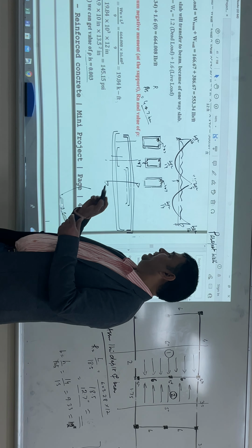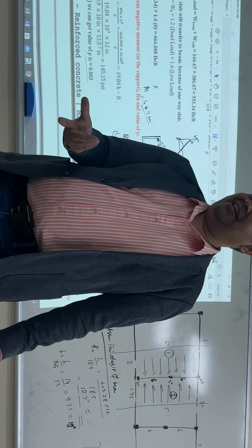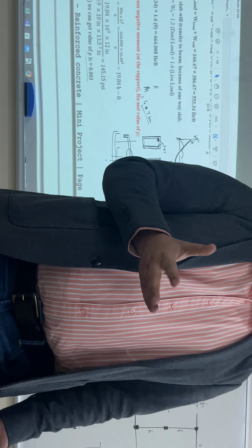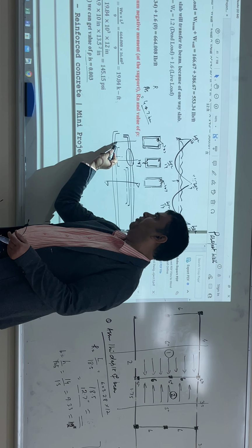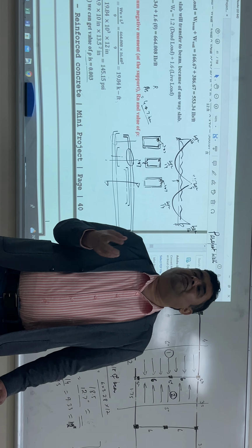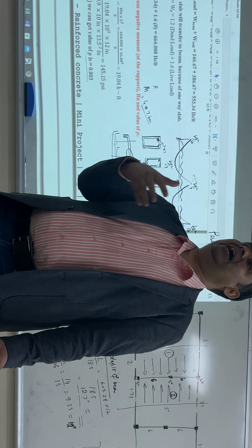But in this area, this reinforcement is unnecessarily provided. It is needed only to support the ring; here it is needed, but here it is not needed, yet you are providing it. And at the bottom it is not needed, yet you are providing it also. So you are providing this reinforcement unnecessarily to the beam. That is why not design it as a doubly reinforced beam, take advantage of this reinforcement, reduce the beam dimensions, and achieve economy.